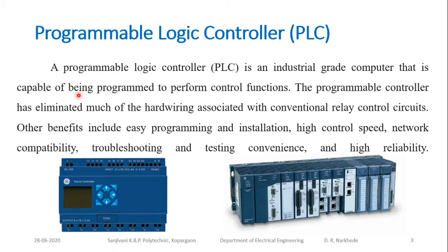Earlier, we used hardwired relay logic for controlling purposes or doing the automation of the machine. But when you use hardwired relay logic, it is quite difficult to make changes in the system. Say if you are going to manufacture a particular model, and there are certain changes in the model, you need to rewire the panel. When you rewire, there are hundreds of relays over there, so it is quite a difficult and time consuming task to make the changes in that circuit. Okay, so that is the main problem.